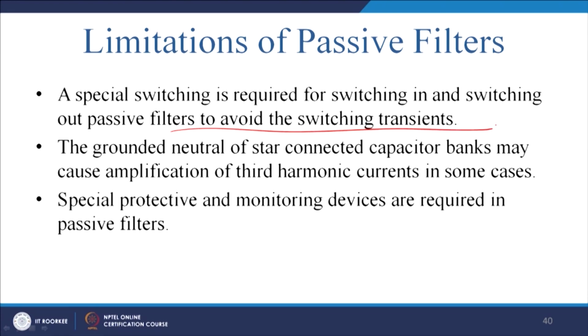We have discussed this in detail; we are short of time here, so I cannot discuss it here. Inserting a capacitor in FACTS devices, please see those applications. Once you insert a capacitor, like a series capacitor or SVC, if it is already charged, generally you cannot always have it discharged totally. So, you require to enter the capacitor bank when it is sinusoidally varying, when the supply voltage and the capacitor voltage match.